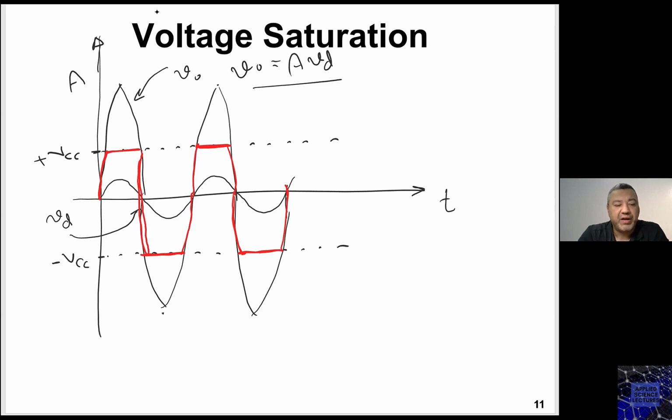With the transformer, at the end you have the power, you're not adding any gain. You are changing the voltage, sacrificing the current, or changing the current, sacrificing the voltage between the primary and the secondary. So at the end, the transformer is a passive device. This operational amplifier is an active device. It has its own source that is increasing the power of the signal. It's a completely different concept.